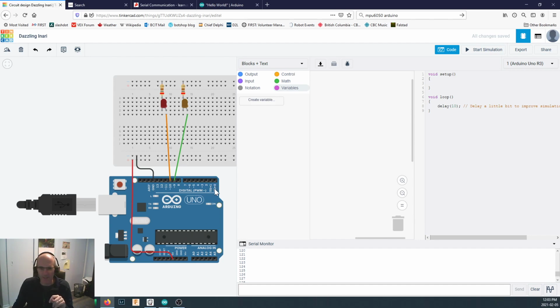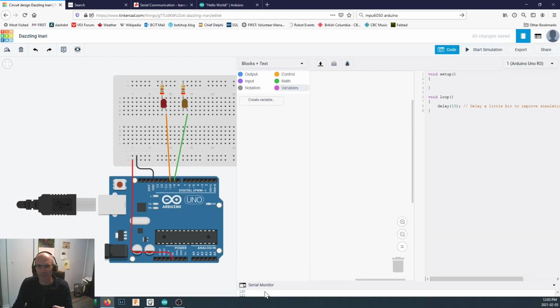Those are connected to the pins on your microcontroller. If you follow the little trace through on the printed circuit board, you'll see they connect to pins on the microcontroller. When you execute a serial communication command with the microcontroller, the pins will flash on and off really rapidly to transmit data, and it goes out to here, but it also comes back to this chip, and this chip interprets it and fires it down this line, and it shows up on your computer, and you can watch it in something called the serial monitor.